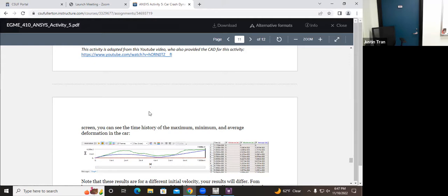So the transformation matrix that you want is ACS on top of the lower arm, and then ACS on the bottom of the upper arm. So you're going to have to do a little more matrix multiplication of these two and eliminate some of the inner ones. Again, I'll give you a hint: you're going to use the answer of part 2 together with the two given matrices in part 4, so that you can get one transformation matrix for the two ACSs.